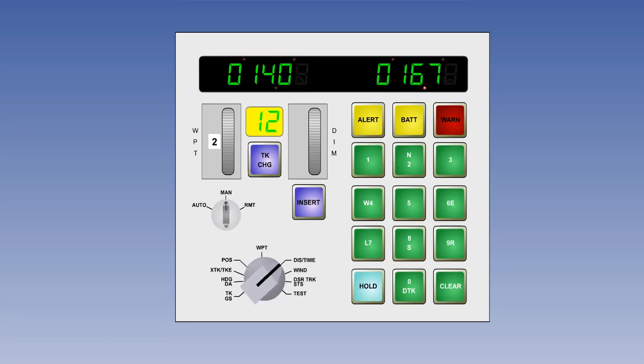With the rotary selector in distance to go and time to go, the left-hand display shows the distance to go to the nearest nautical mile, and the time to go to the nearest 1/10 of a minute from present position to the two waypoints along the route, between the two waypoints selected in the From To LED display. The time to go is calculated from the present ground speed, and the system is responsive to changes in ground speed. If the thrust is reduced as the speed trickles off, the operator can see the time to go increasing as he watches.